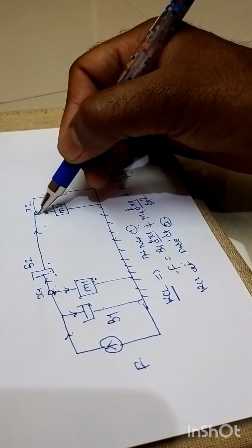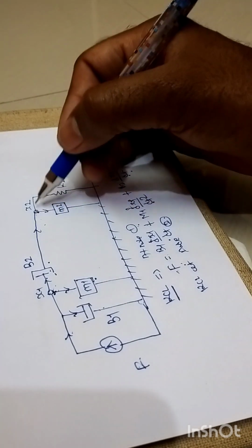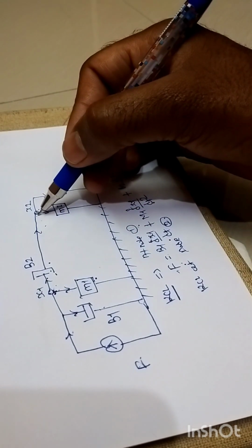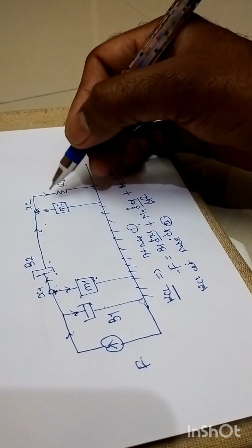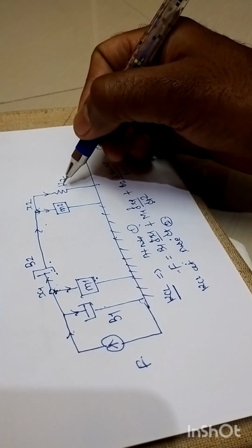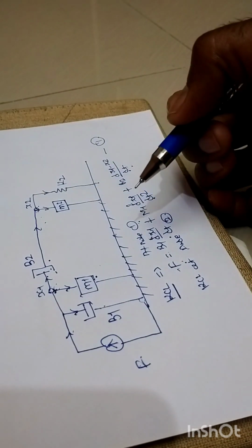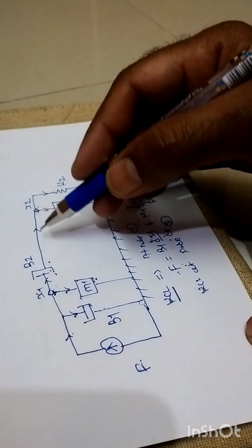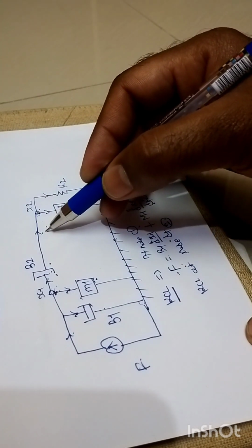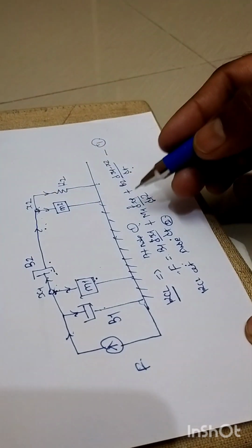This is the direction of force, which by default is incoming, because it is going from x1 to x2, means it is incoming towards x2, and the directions of these two forces belonging to m2 and k2 are outgoing from this node, right? So in order to write the system equation, as there are three branches, this branch is incoming, and the remaining two branches are outgoing from this node, right?